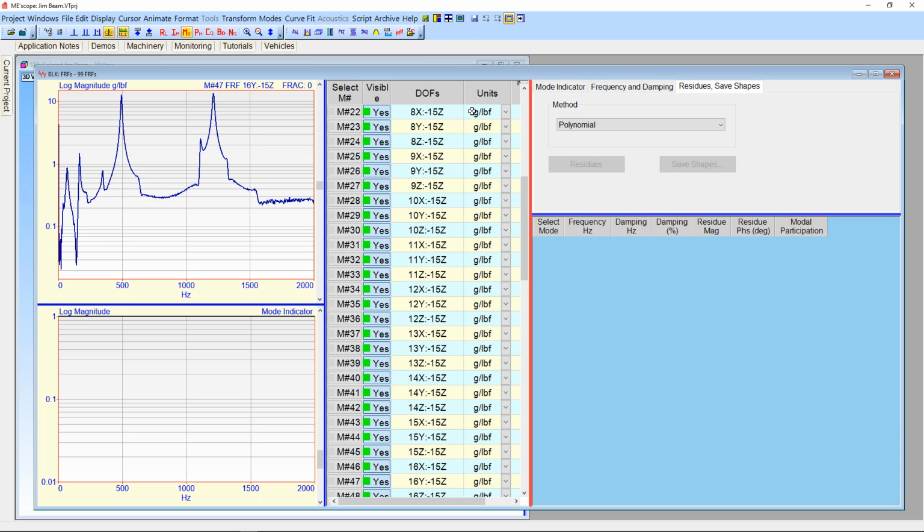So it's basically removed the frequency content of the force, and the FRFs simply have, at each frequency, the response of the structure due to the force at each frequency. That's why we use FRFs, because when I see a peak in these measurements, that peak is due to the resonance. It's not due to a peak in the force.